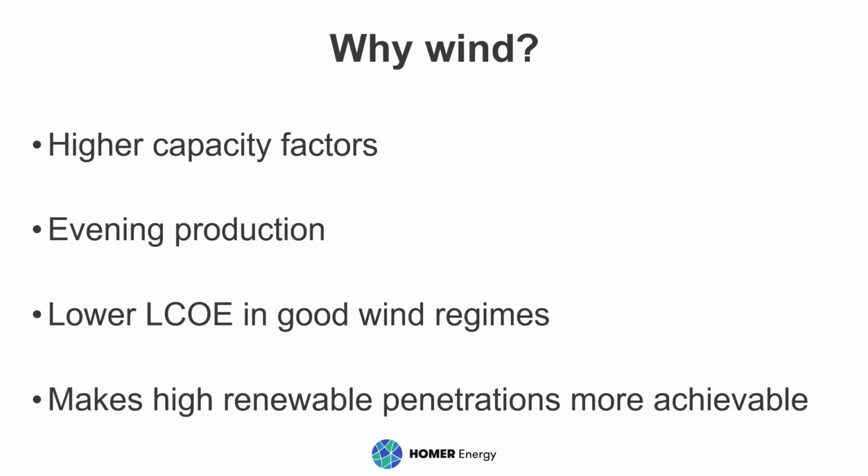So just to wrap up my portion here, and we can get to the questions and answers. So why wind? Well, solar has capacity factors of 20%-ish. That's pretty good for solar. You can get maybe a little higher, and then I know they're putting solar in the UK and getting even much lower capacity factors. But wind can often have capacity factors of 30% or more. So that's a really important factor when you're comparing technologies, because it justifies a higher capital cost if you're getting a higher capacity factor out of it.